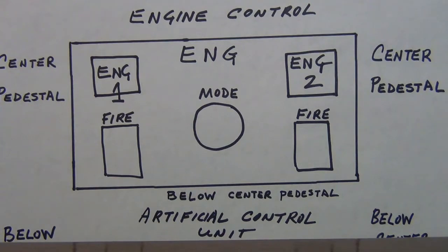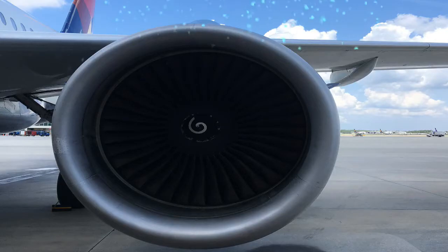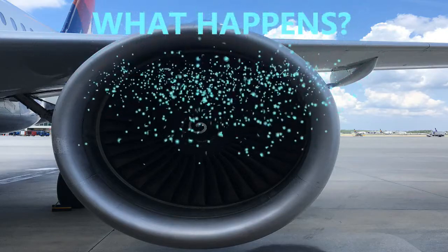The switches, when you have the engine master control switches on, are interfaced with a couple of components. One of them is going to be your fuel shutoff. Obviously, when you start the aircraft, there has to be the instruction or command to get fuel to the engines. So with that automatic position, when engine master control switches are on and you're not in manual start, you're going to have the shutoff valves start to open.